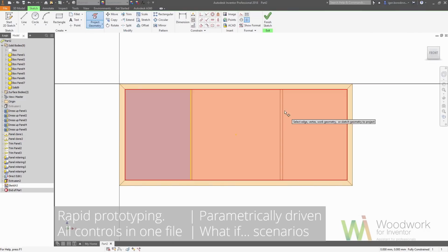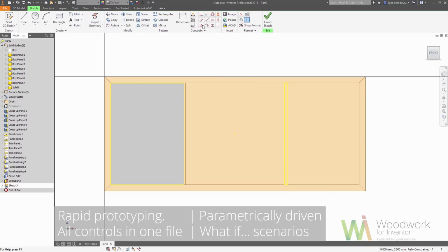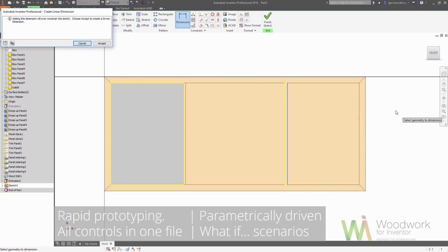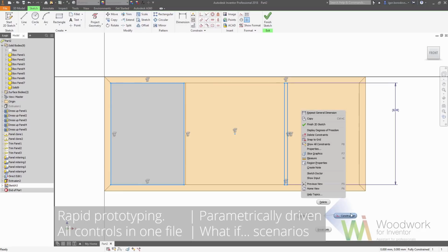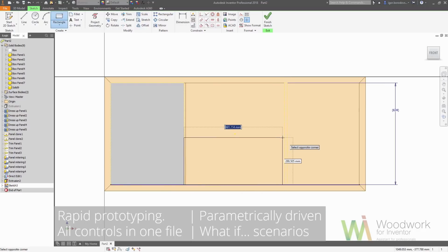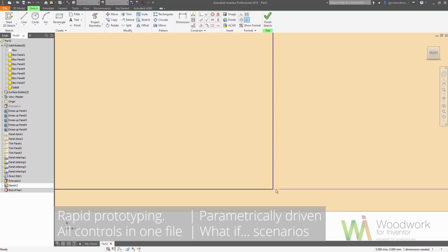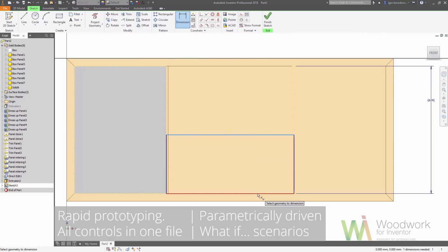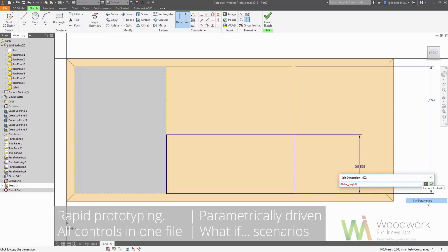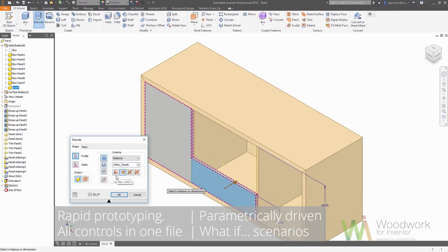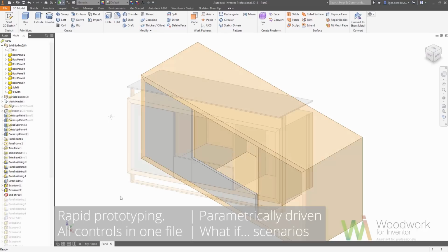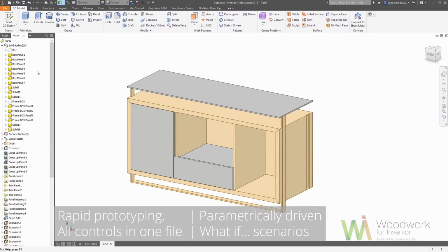Okay, now let's project another separator, and we want to know how much space we have here. So we'll make a driven parameter, niche height, and we will use it to define how much space for the drawers we have. Okay, let's draw a facade of one of them. Set its size, which would be the size of the niche divided by the amount of drawers. Very simple math. Okay, that's it. Let's make an extrusion. And basically, after a while, that's what we have.